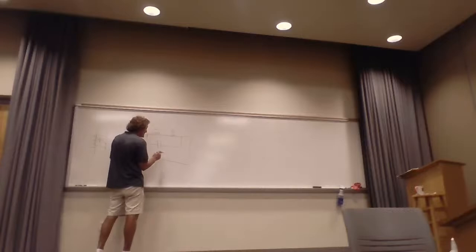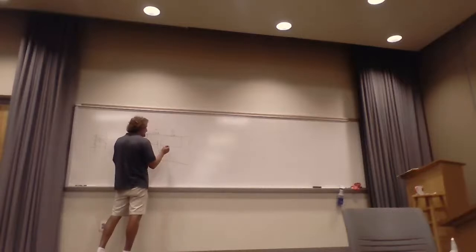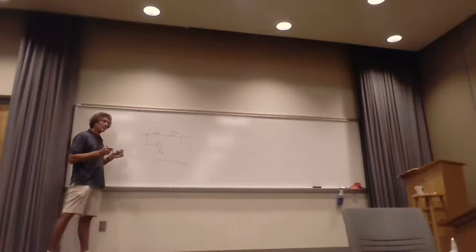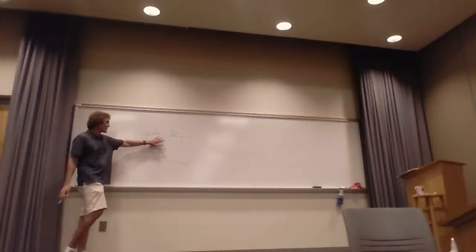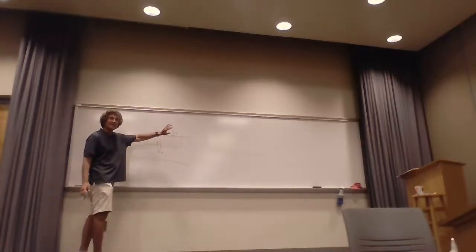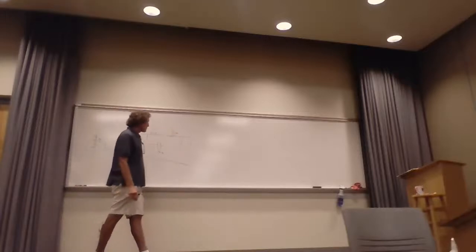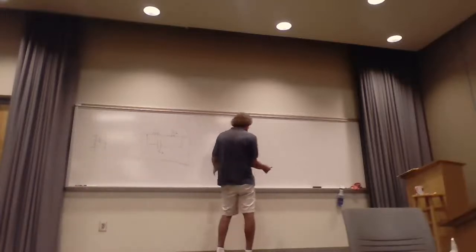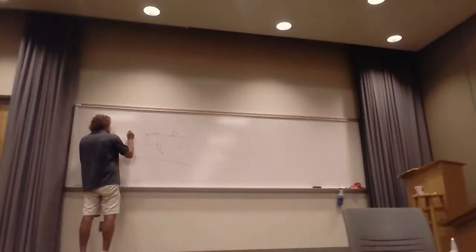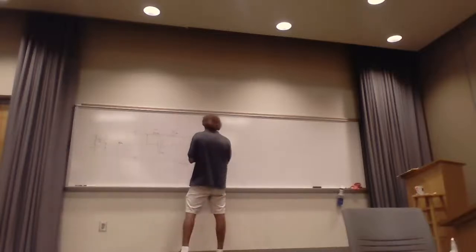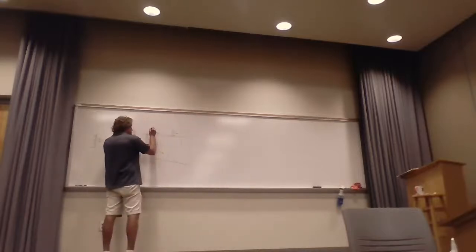So what we do in general, they call that CX and RX, I think, in his book. The inductance is what we want, but we can't get away from the fact that there is an inherent resistance and capacitance. At low frequencies, though, you can forget about that capacitance, and that resistance is basically extremely small. So when we say, what is the impedance between these two terminals? This is in his book. We can do it with S. So this will have an impedance of SL.